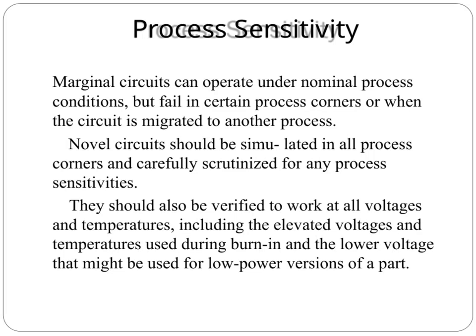When we talk about process sensitivity, we're referring to how certain circuits behave under variations in manufacturing conditions. Marginal circuits might work fine under standard nominal process conditions, but they can fail when exposed to specific process corners or if they're shifted to a different fabrication process. This is why novel circuits need thorough testing across all process corners. It's not enough to check their performance at just one set of conditions.